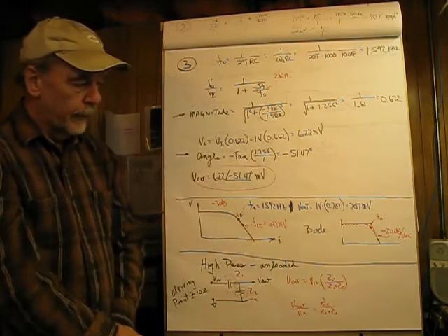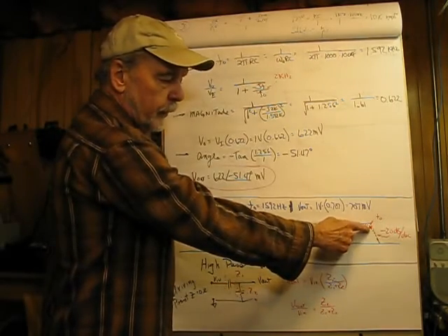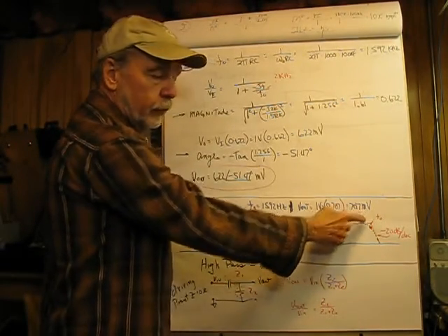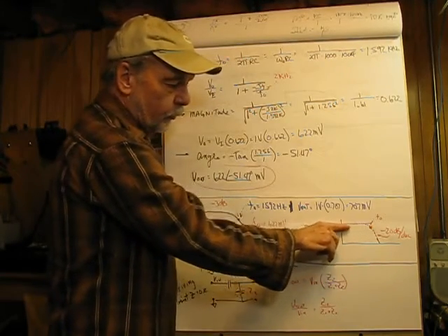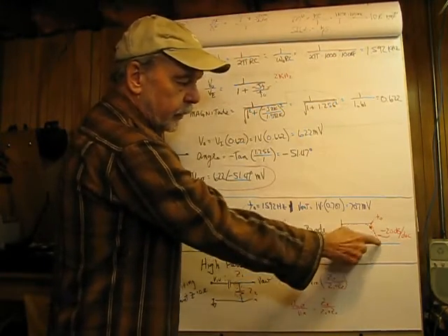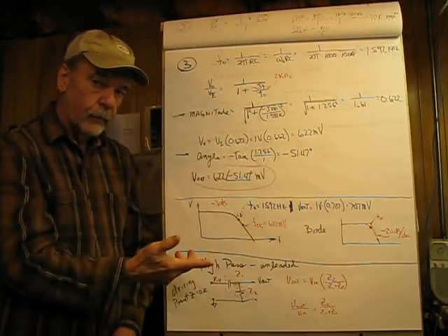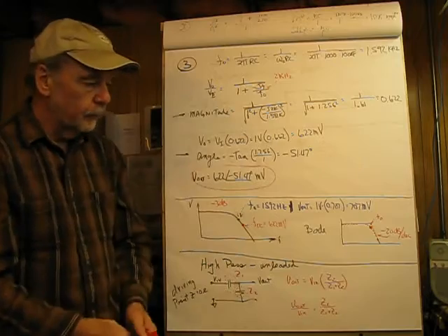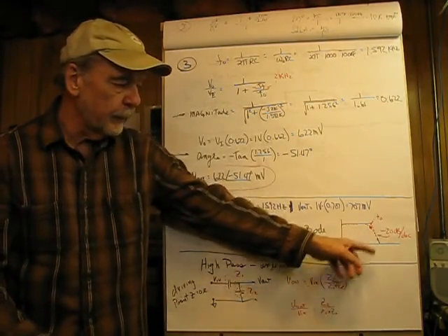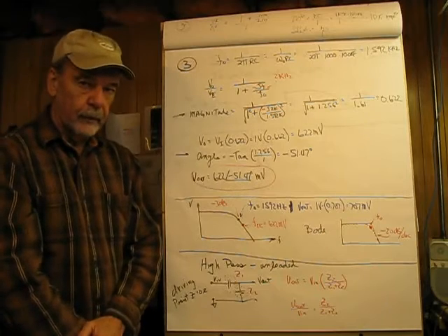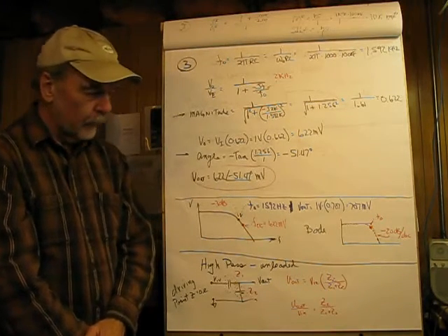And if we were to draw that in a Bode plot, we would take our critical frequency and bring a line directly vertical so it intersects with this horizontal asymptote and use a straight edge on this guy. Pick a second point here, which is a factor of 10 out. So that's a decade out. Put a dot 20 dB down and connect this point with that point, and you have the Bode plot. And Bode plots are asymptotes and they're straight lines.